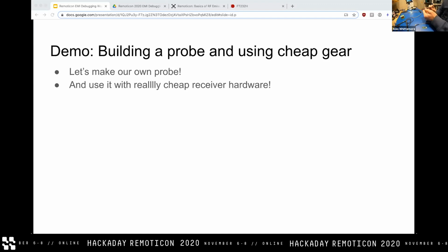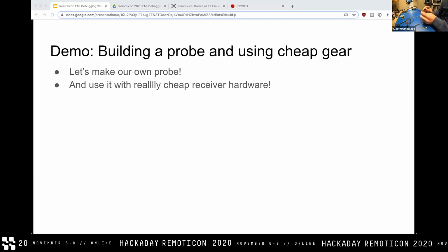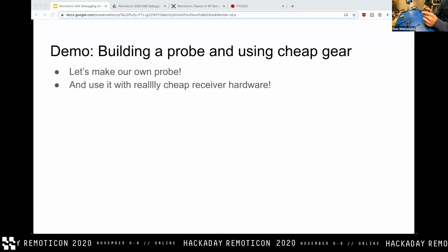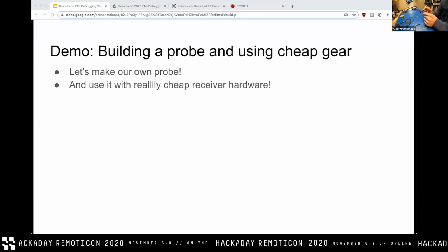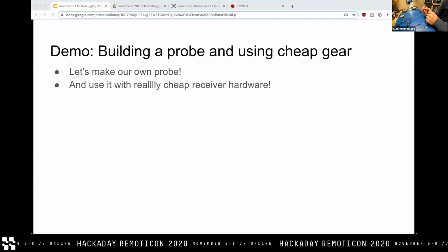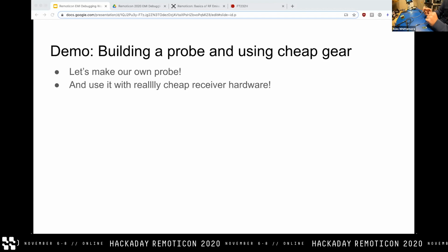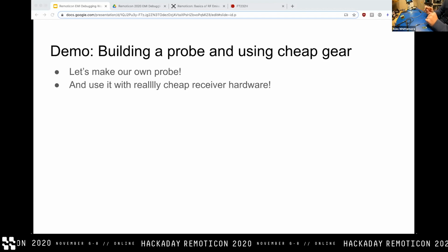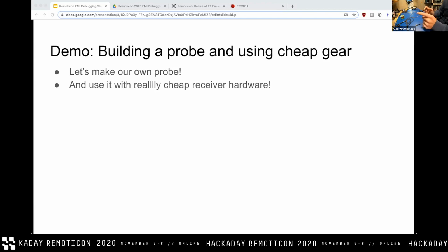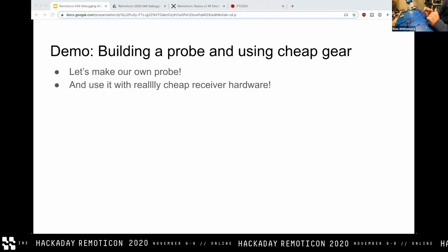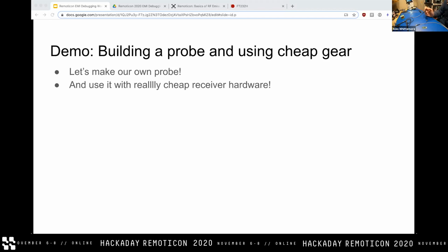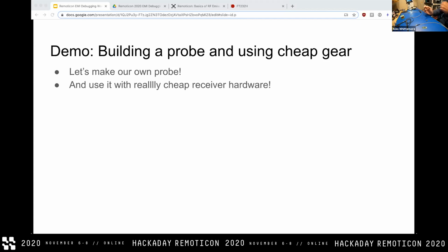This probe is designed in such a way that there's a magnetic loop up here, and this is sensitive to magnetic field through the probe, through that open loop, but not at all to incident electric field, because you're trying to measure just the magnetic field. You don't want this whole thing acting like an electrical antenna and receiving electric field as well. So this probe is designed in such a way that there's a conductive shielding over the entire thing, though split so that there's still a current loop for magnetic field to induce a current and therefore a voltage.